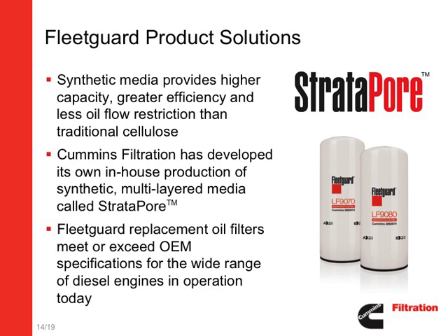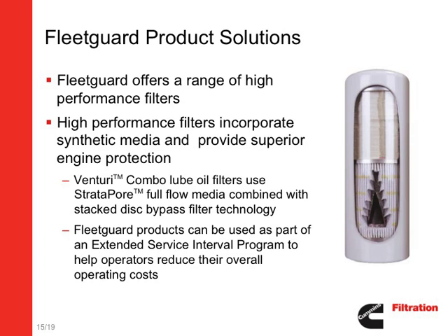Stratapore has a micron range from 2 to 25 microns, depending on the application. Compared to the average 40 micron rating of cellulose media, the Stratapore media delivers much greater performance. Regardless of the filter selected, all Fleetguard replacement oil filters meet or exceed OEM specifications for the wide range of diesel engines in operation today. In addition to its line of standard filters, Fleetguard offers a range of high-performance filters. These filters incorporate synthetic media and provide superior engine protection.